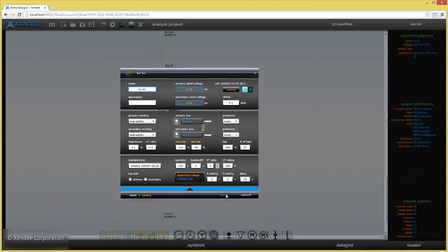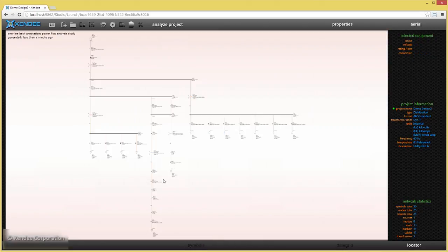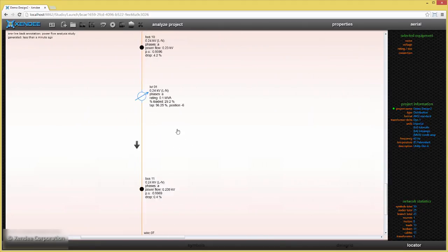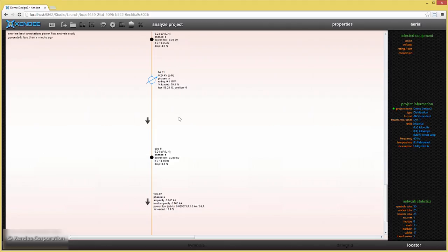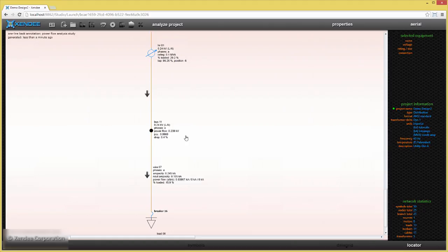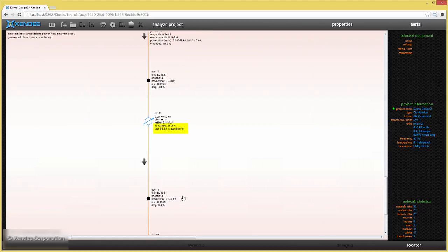Once these settings have been defined, we can simulate a network and see the voltage regulation impact. So let's go ahead and perform a snapshot power flow on this sample network to see voltage control along with the calculated tap position of the line voltage regulator for our voltage control objective of maintaining 240 volts at the load. You'll see that tap position has been calculated and voltage at our load is now within the bandwidth setting. This concludes our brief tutorial on line voltage regulators.